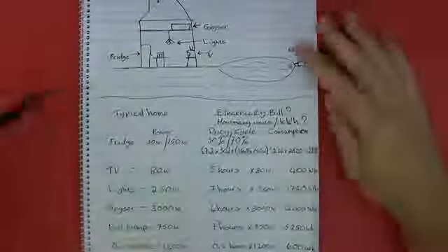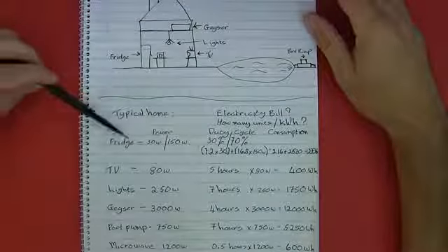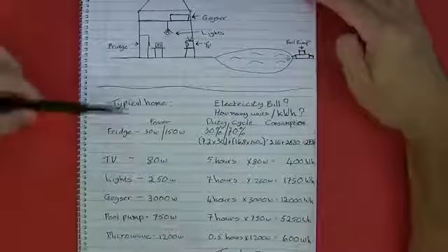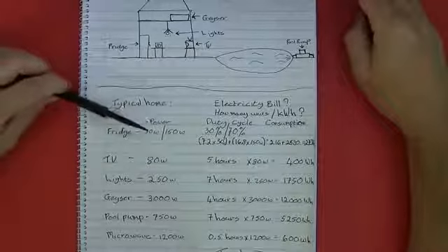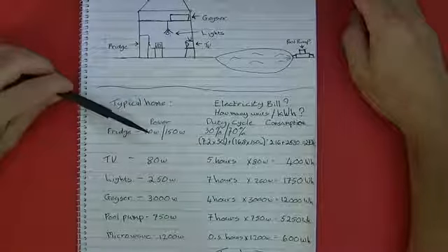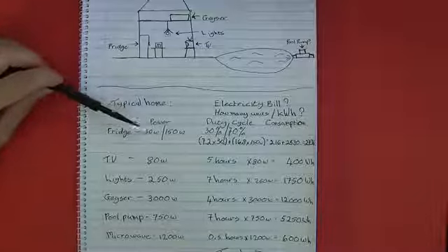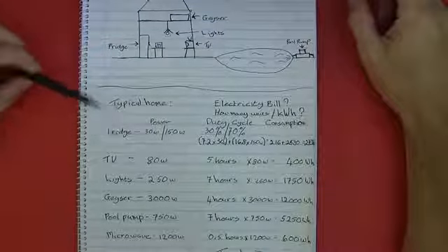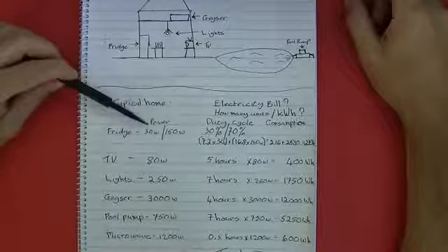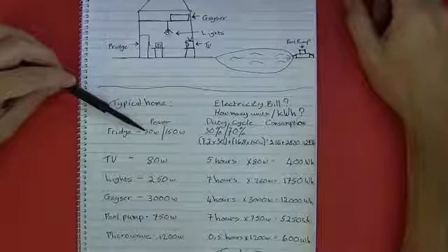Right, so if we go and list an item, the things to note here are that all the items in your home will have a certain power rating. So the one thing is to understand that power rating. The next important thing to understand is the duty cycle. And here, just to paint an example, your fridge will have a power rating, and in fact it'll probably have two power ratings. It'll have a power rating when it's not actually doing its cooling. It's almost like an idle mode.